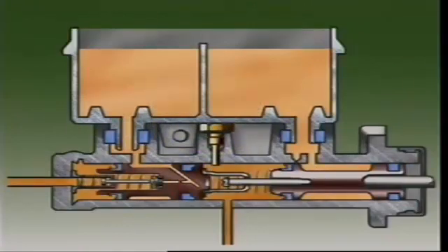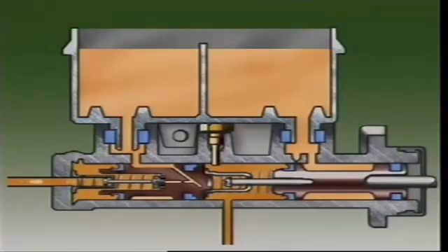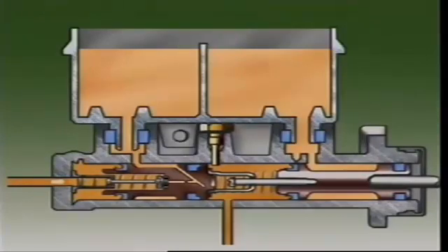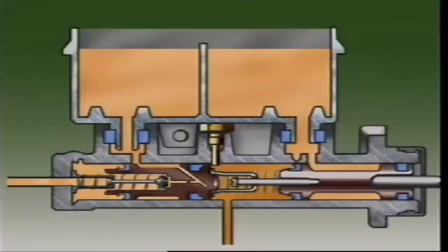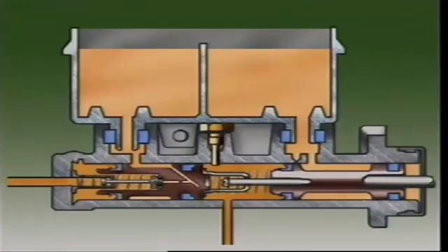If braking conditions are such that the hydraulic modulator must return brake fluid to the master cylinder, then for the front brake circuits, fluid is returned to the front section. This forces the secondary piston back against the force of the primary piston spring and the rear brake pressure. If enough fluid returns, the center valve opens and allows fluid to return to the reservoir. If fluid is returned from the rear brake circuit, the secondary and primary pistons tend to be forced apart.